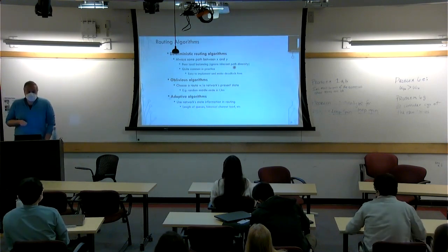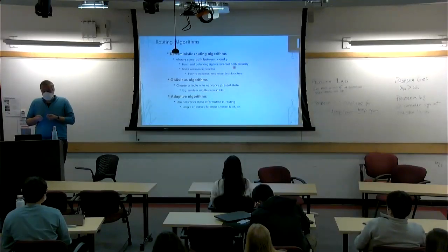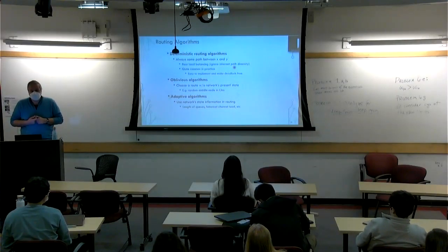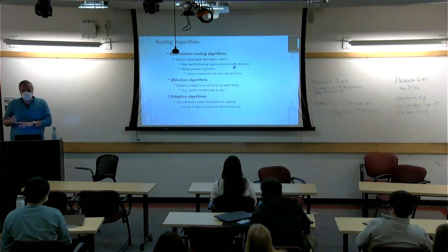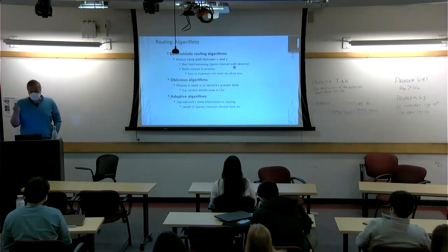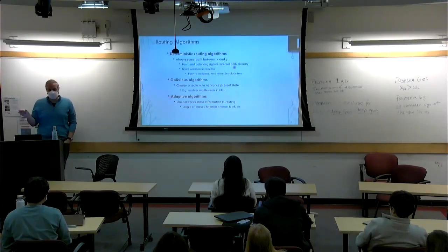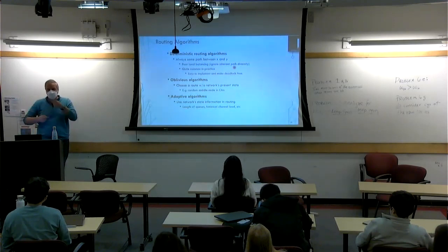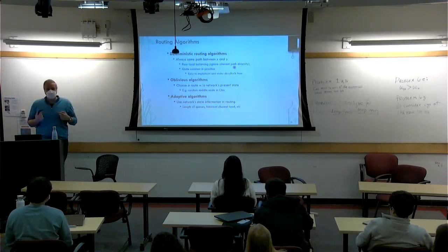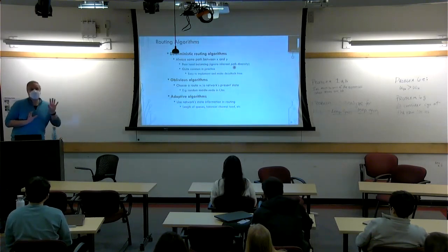But the nice thing is that it's quite common in practice, and easy to implement because of the deterministic nature, and also you can make them deadlock free, meaning that the deterministic route will make sure you don't have the feedback deadlocks that are sometimes possible if your algorithm is less deterministic, right? So you can't really verify if you're going to run into this condition.